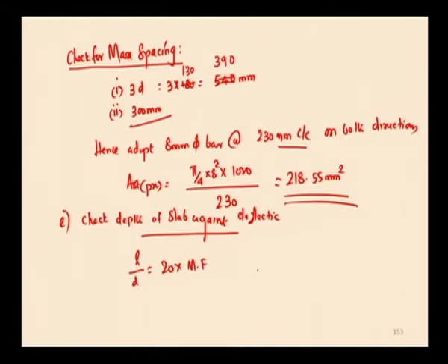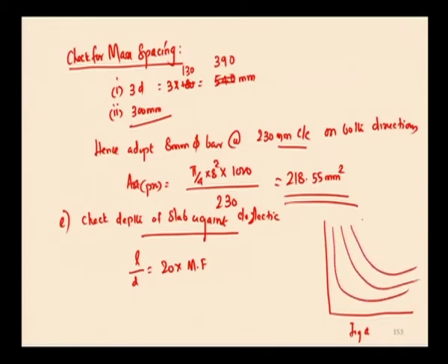I have already told you that this modification factor has to be found from figure 4 of IS 456:2000. It has several curves, 4 or 5, depending on the stress developed in the reinforcement, and the graph shows the modification factor versus percentage tension reinforcement.